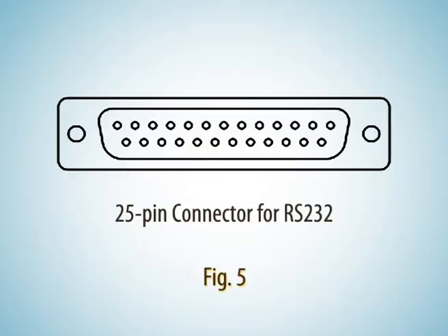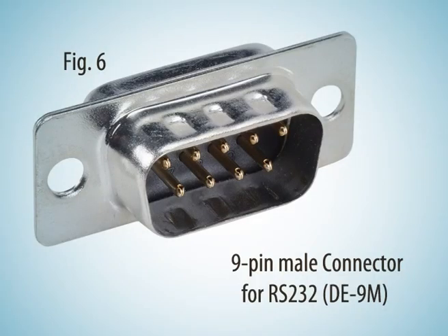An image of the 25-pin subminiature D-type connector popularly used in the decade of the 90s is given in figure 5. The standard specifies 20 different signal connections on this. Since most devices use only a few signals, smaller connectors can often be used. Personal computer manufacturers replaced the DB25M connector by the smaller DE9M connector shown in figure 6. Different pin numbers were used for the signals discussed in the next section. This connector with varying pinouts became common for personal computers and related devices.